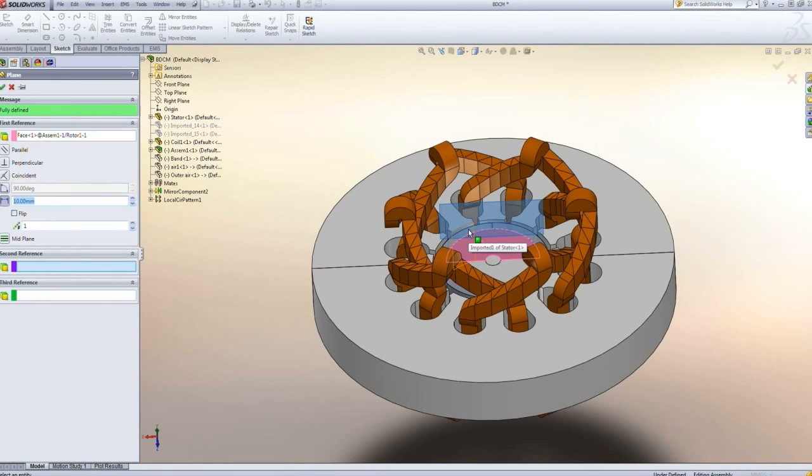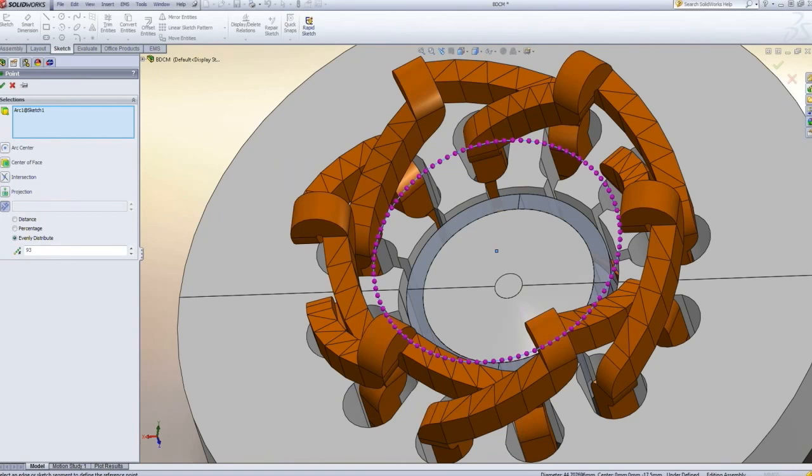I do not need to go through the process again. All I have to do is drag and drop the study, give it a new name, say neodymium 52, and then say yes. Now what happened here is EMS copy-pasted everything for me into a new study. So now I can do any modifications I want in here without affecting the results from the other. So everything that happens here does not affect what happens there. So I get to keep my old results and play around with the new ones.